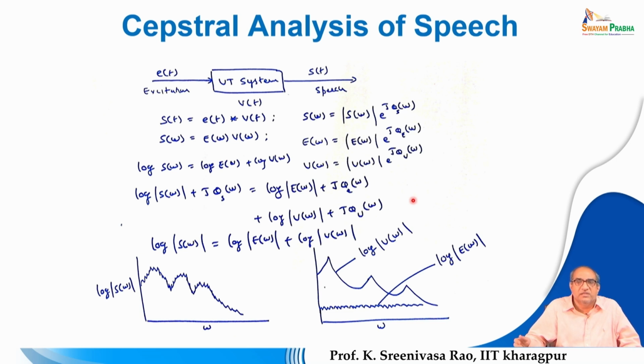So the linear prediction coefficients captured in the analysis phase represent the vocal tract system response, whereas the error signal that is the outcome of the linear prediction analysis can be viewed as the excitation signal.